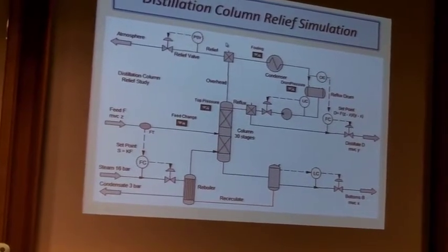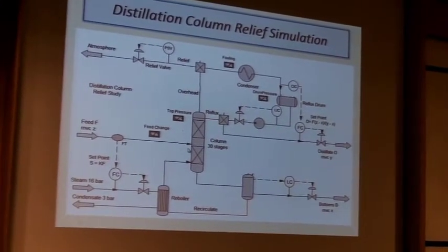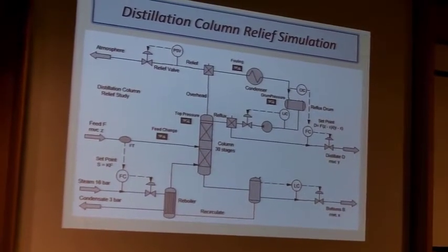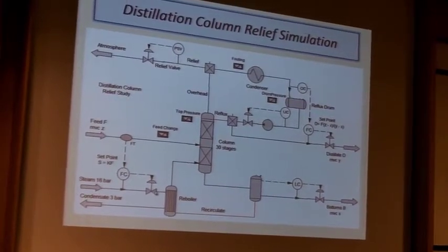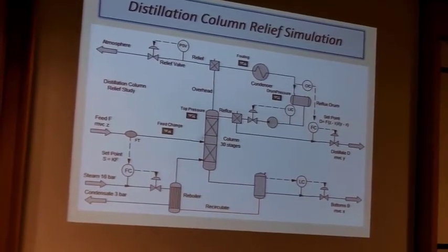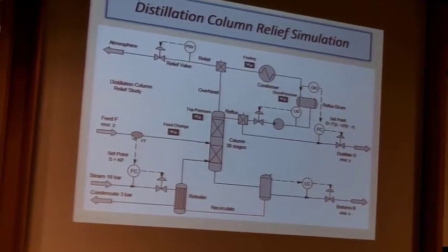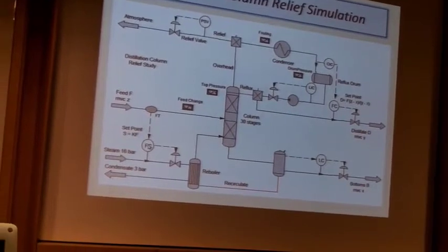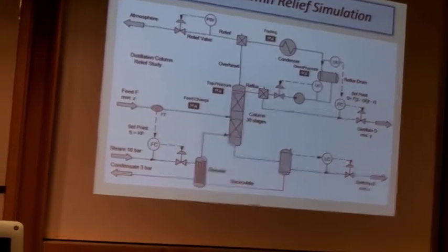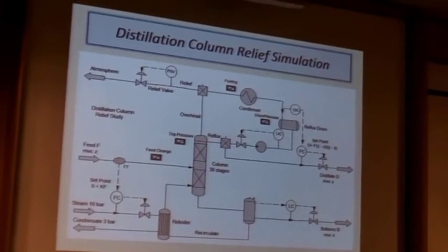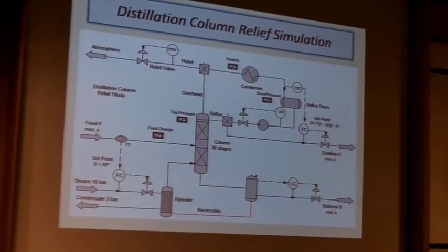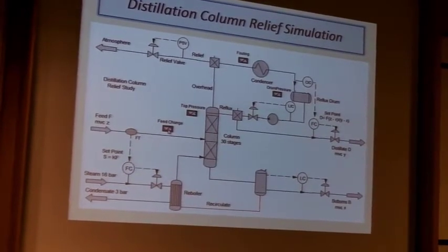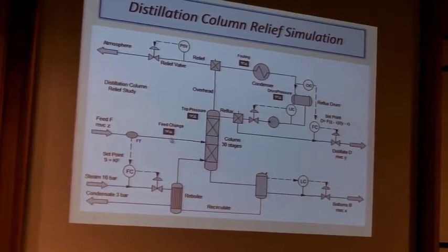Distillation column. Typical distillation column. Vertical recirculation, natural recirculation reboiler. Steam. Feed. The steam is ratioed to the feed. That's done in Excel. So I can make this simulation talk to Excel, so I can control it from Excel. These are little modules to change feeds, they're little ramps that we can use to change values.